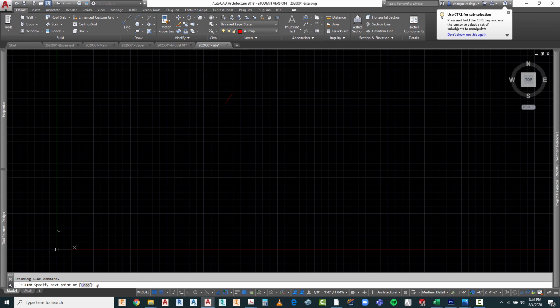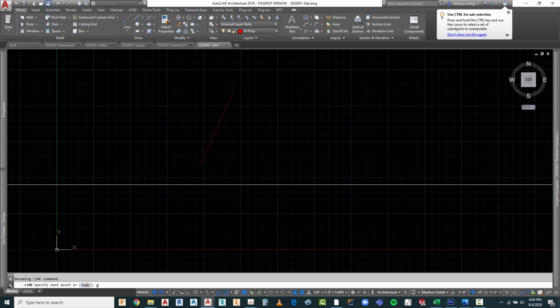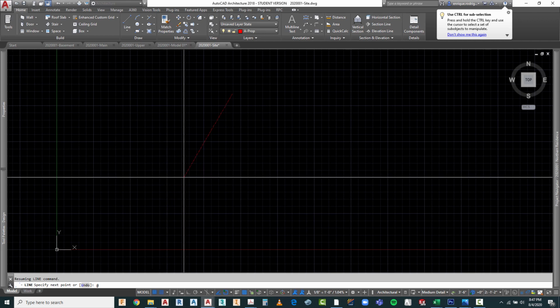If you could see the command bar down here, it starts with the at command. The first thing we're going to do is give a distance, which is 112.93, and we need to give it the feet because our units are still in inches. Then we do the greater than less than signal, and now we give it the bearings.